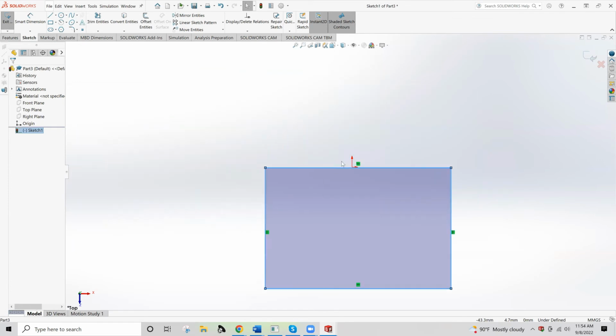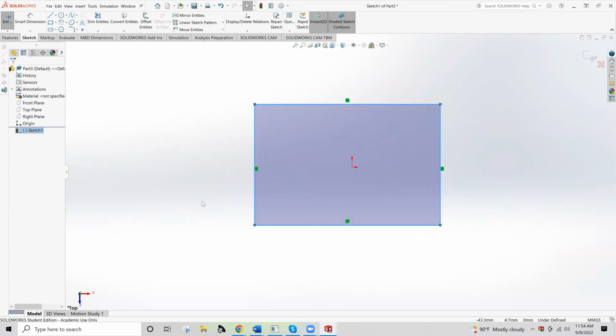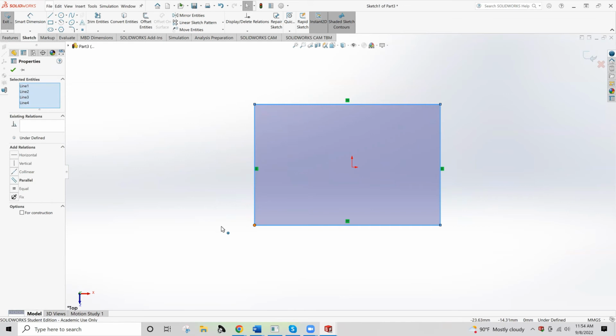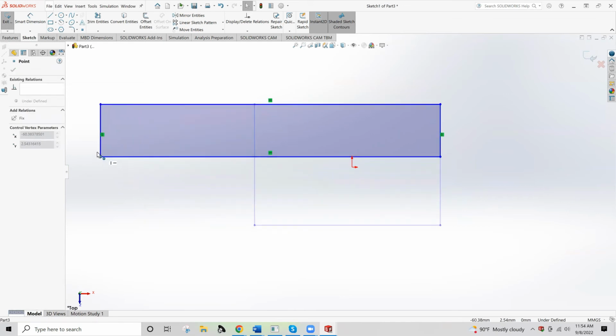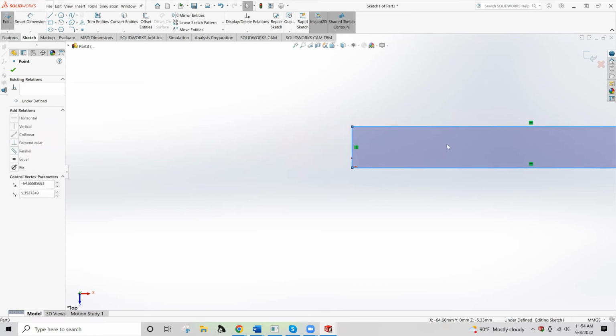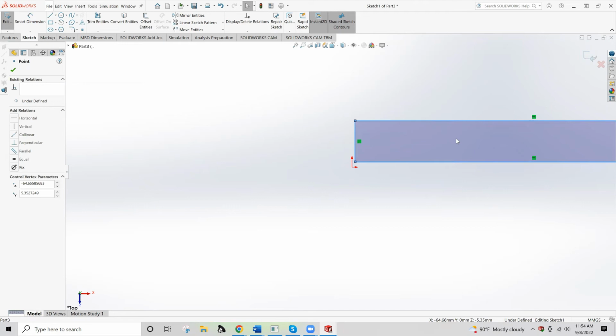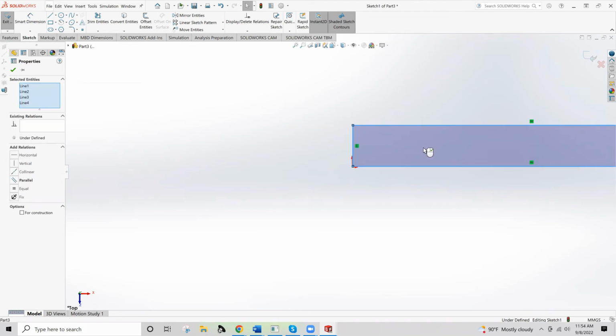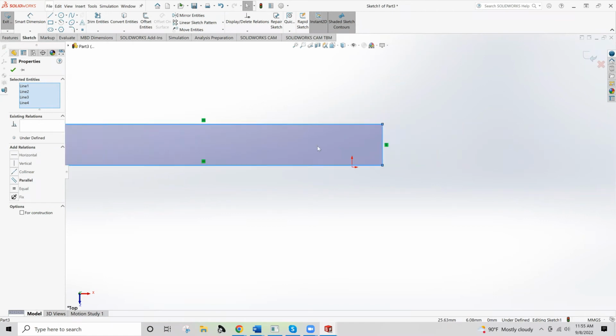So you can just free drag it if you completely botched it and forgot to do the view. You can also do a kind of free dimensioning to get it closer to what you want. But it's not necessarily going to snap to the origin or anything like that, so you don't have an easy way to make that happen.